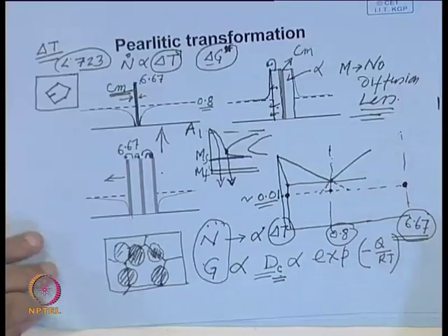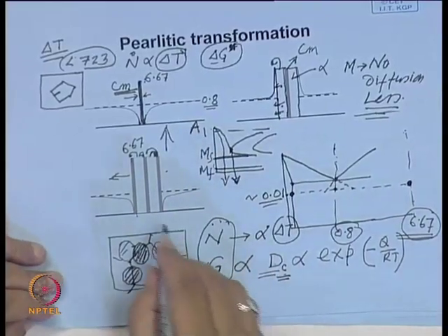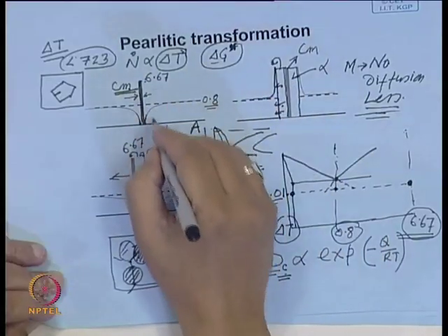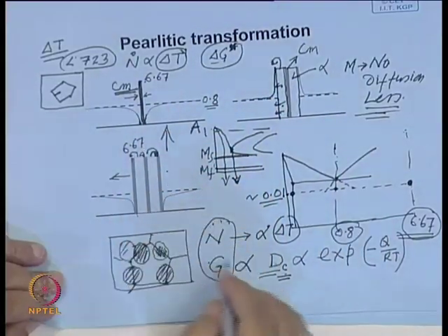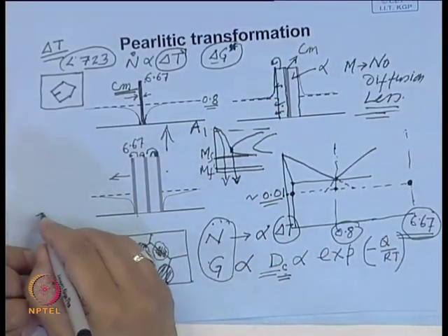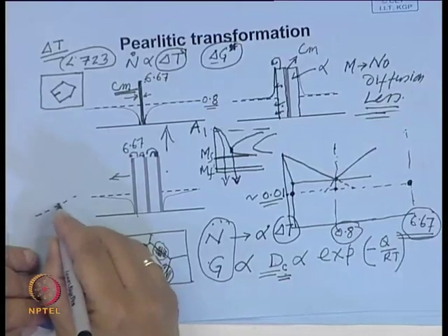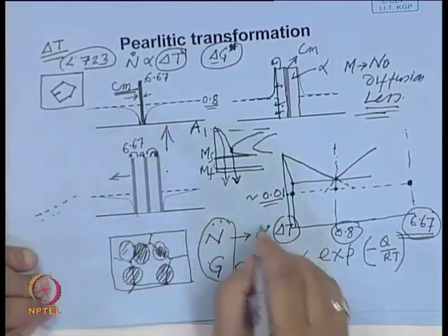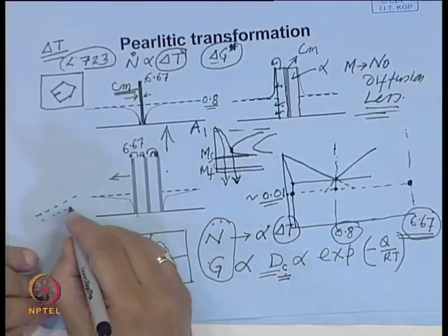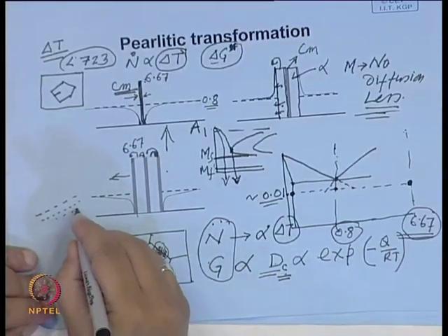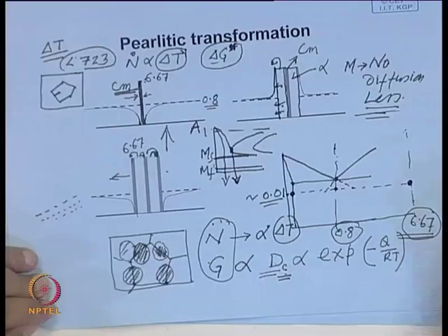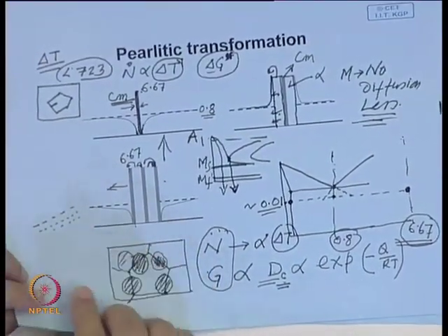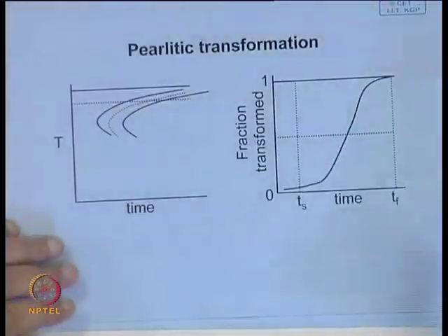Whereas in the case of a bainite structure, there is diffusion, but you can see that in pearlite the carbon atom moves over a large distance, and in bainite the carbon atom does not have to move a large distance. So that is why at a lower temperature when bainite forms, you have such a finer structure, such small platelets of cementite or epsilon carbides. There the diffusion distance is much less.